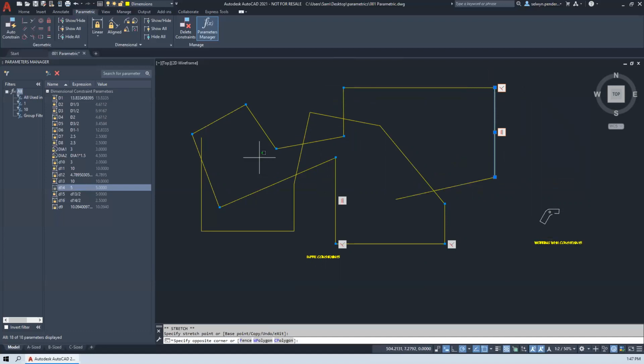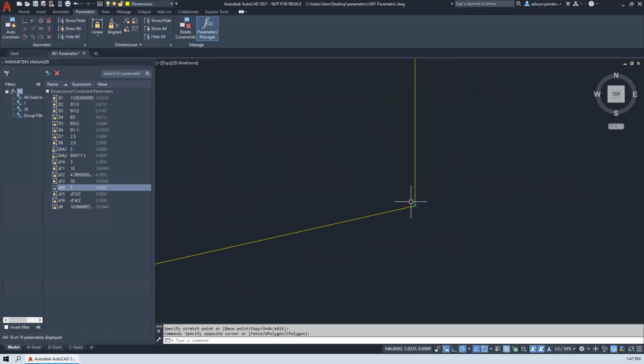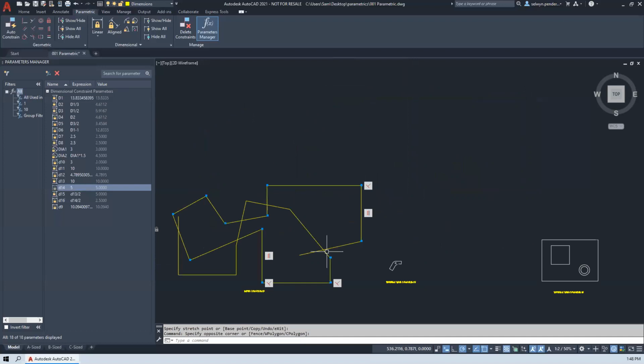You'll see also, as we were drawing lines, it's put these small blue icons in here. That's your coincident constraint. Because I drew lines, it's putting coincident on each of them. If I did polylines, it doesn't need to do the constraint.